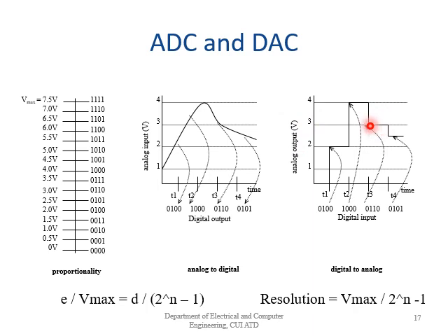For example, if we have analog output, we are mapping from digital inputs. So the digital input is 0110 and the analog output comes to be 3 volts. Just put D to be 6, n as 4, and V max 7.5, and you are going to get an analog voltage of 3. So this is how you can map analog to digital and digital to analog. So keep in mind this formula.